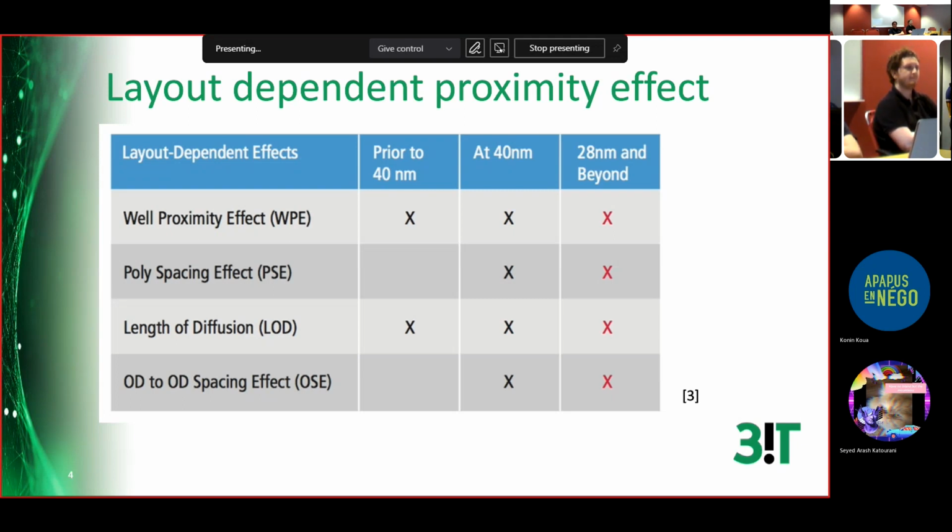For example, if you have your diff pair, let's say this one A, this one B, and you do the layout and make everything match, but for this one the poly pitch, the pitch between the polys, is X, and for the other you take a distance Y that is different from X, they will have different performance because the poly pitch is not the same.